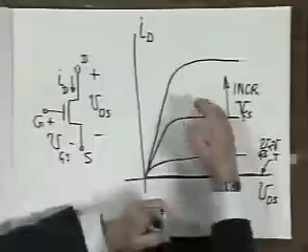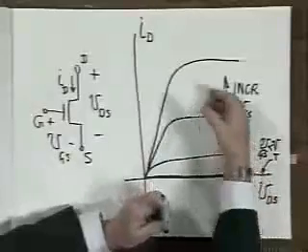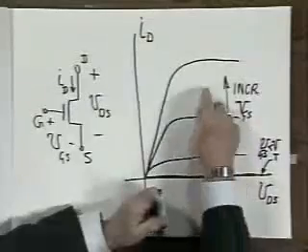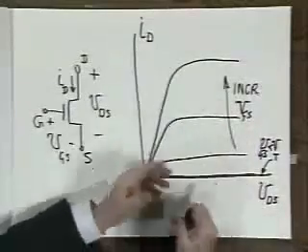These are always represented with a few drawn, of course, but if you look at it on a curve tracer where you can shift the gate to source voltage continuously, you find simply that this is a curve which moves upward with increasing gate to source voltage, and depending on the increments you choose between these various values, you can have as many of those curves as you please.